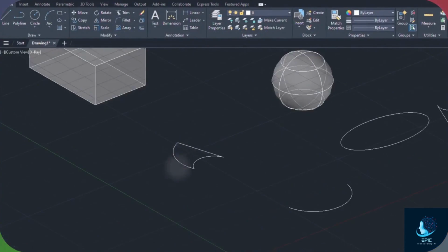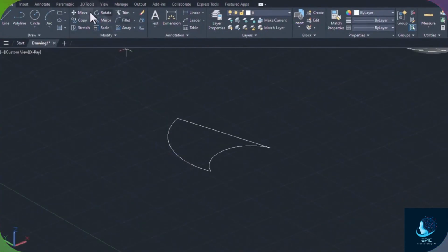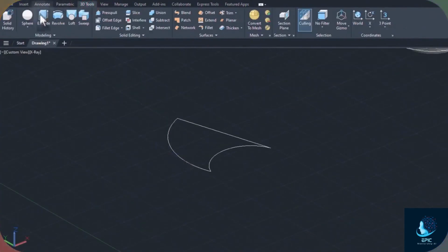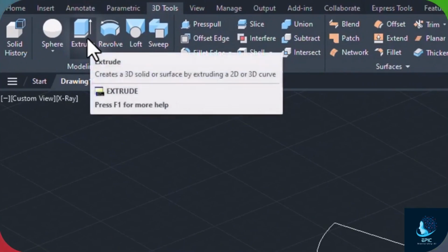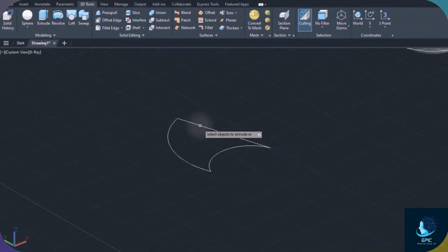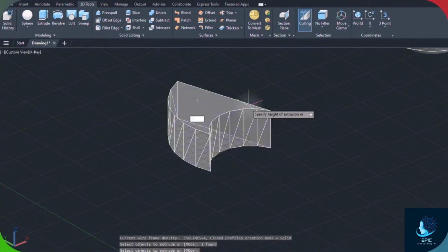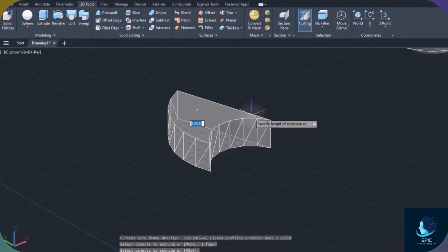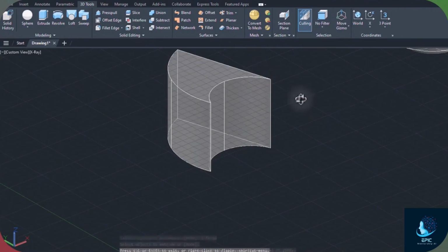You can create more complex 3D solids from 2D drawings. For example, the Extrude tool adds extrusion to a 2D drawing laying on the ground plane. Just select the 2D object, apply with Enter, and set the extrusion to build the 3D object.